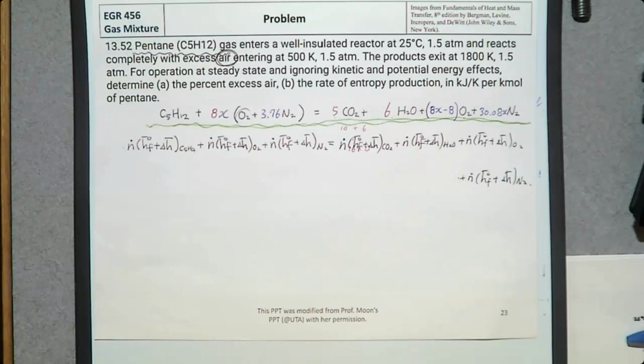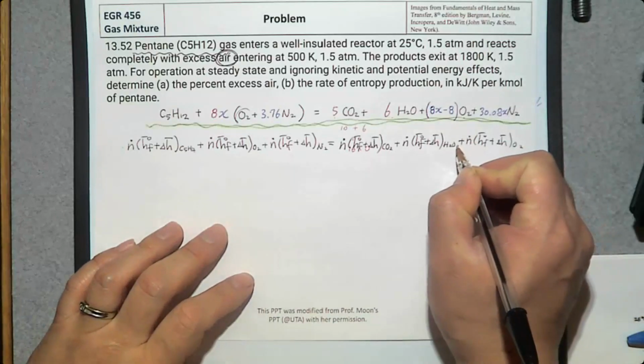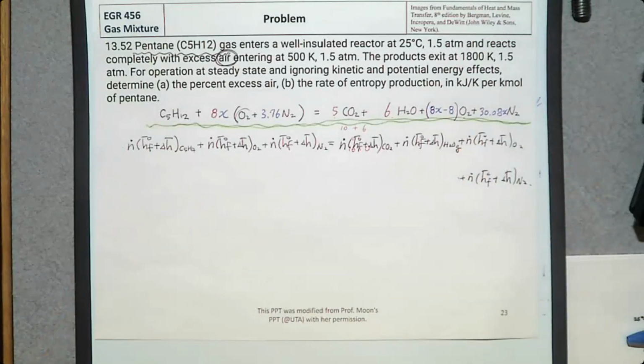Of course, you can make a PV diagram or TV diagram to determine the phase, but at this low pressure the saturation temperature is close to 100-something, right? So when the temperature is 1800 Kelvin, there's no way the water exists as liquid. So it's water vapor. I'm going to say G, yes.